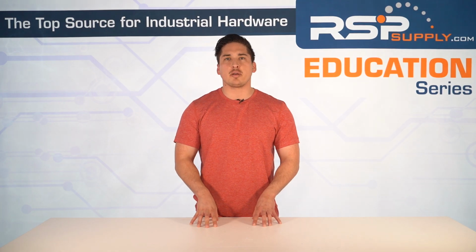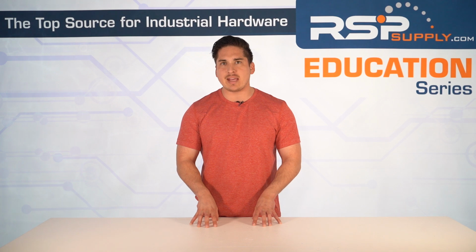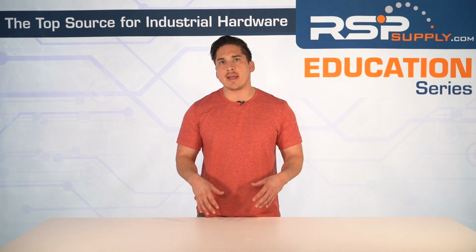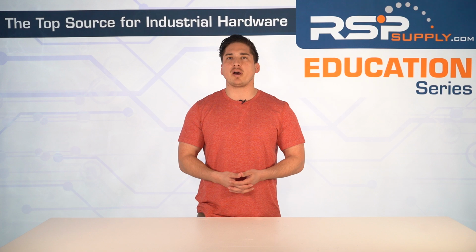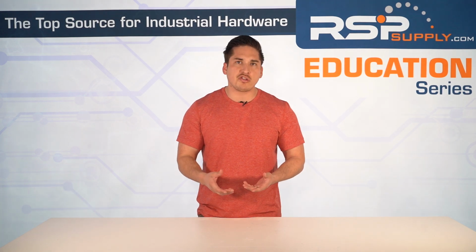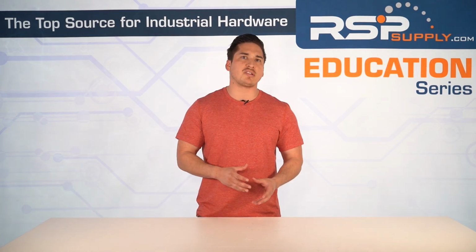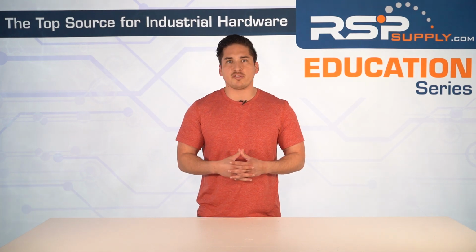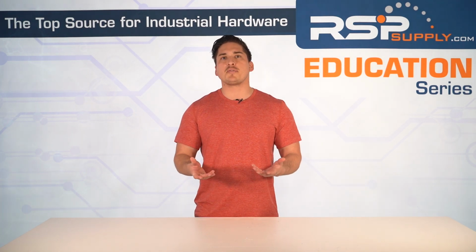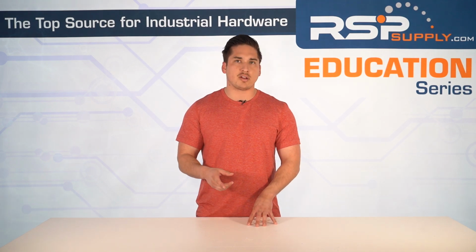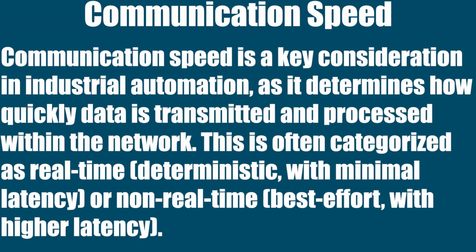So when discussing industrial communication protocols like Profinet, Ethernet IP, Modbus TCP, OPC UA, DNP3, EtherCAT, Profibus, and HART, the factors of communication speed, network topology, and industry preferences are critical in selecting which protocol is best suited for any given application. We're going to give you a detailed breakdown that's framed in the context of industrial automation. Communication speed is a key factor since it determines how quickly data is transmitted and processed within the network. These are often categorized as real-time or deterministic with very minimal latency, or non-real-time, best effort